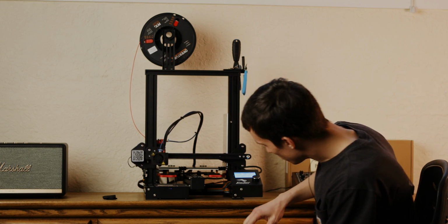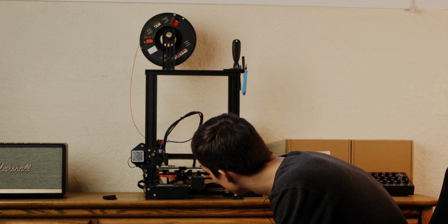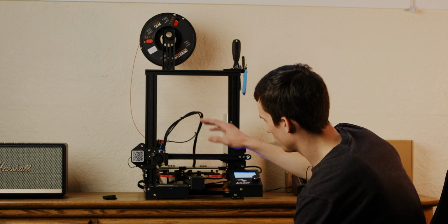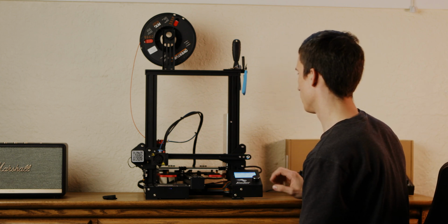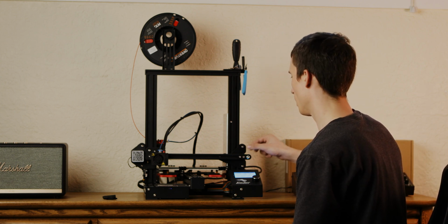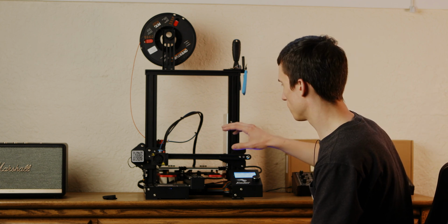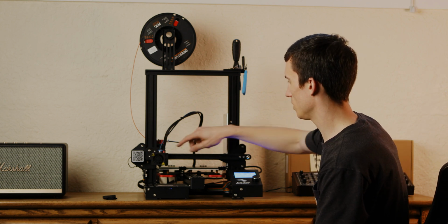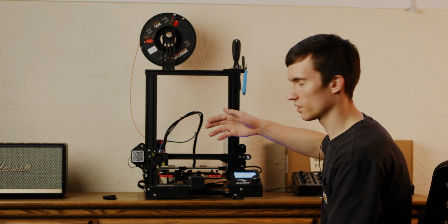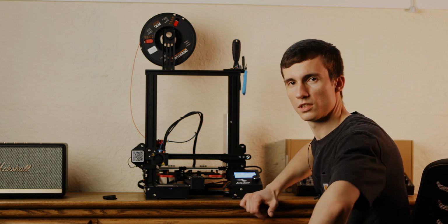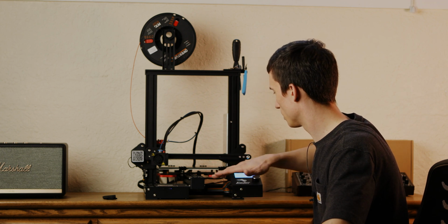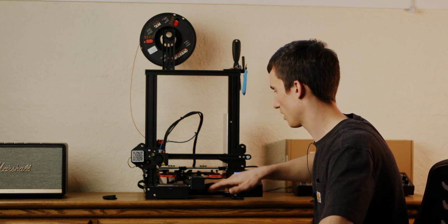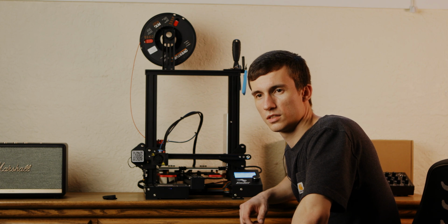There it is. Okay, so I just hit the limit switch, and that's homed. And I already did all the other axes. When I was moving the axes around, I felt for the resistance of these bearings, and to me it feels like nothing's loose, nothing's wobbling, and the travel of all these linear actuators is smooth.